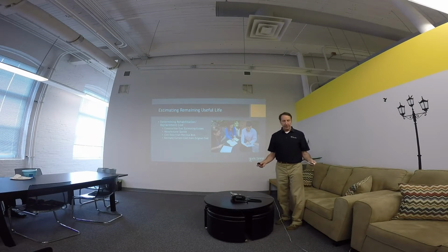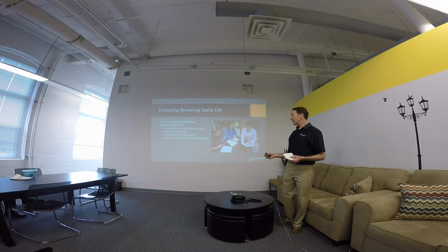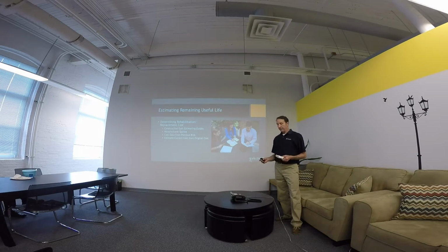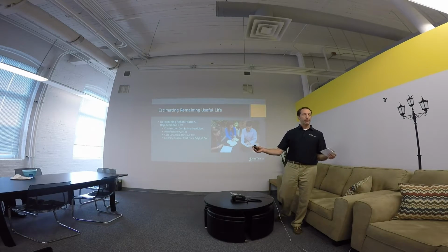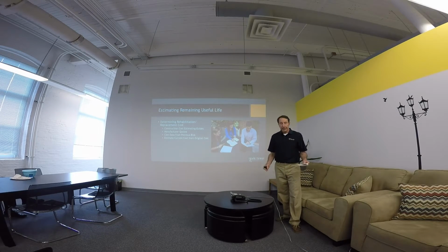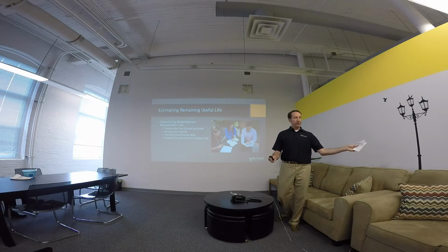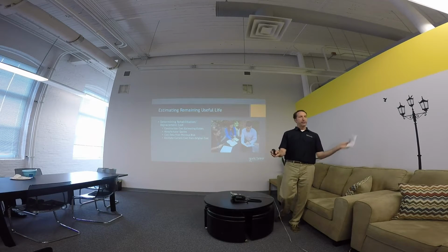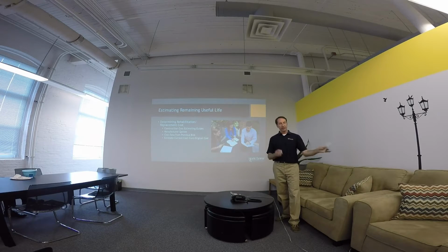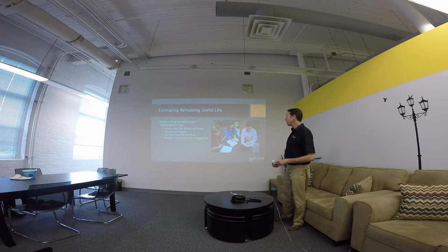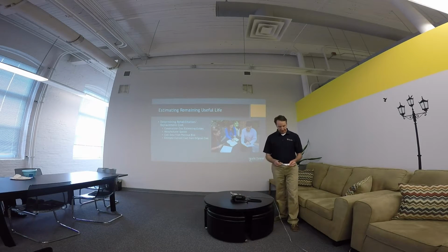We understand the useful life, how long it's going to last. The next thing we need to look at is the cost. How much is it going to cost the town? The town may have X amount of dollars each year for sewer repair, so then we have to prioritize those repairs. We may have a line that's failing just as much as another one, but this is the main line and this is a little line going up to a cul-de-sac, so we're going to put that one off because we don't have enough money to do both. That's typical in the prioritization of these projects.